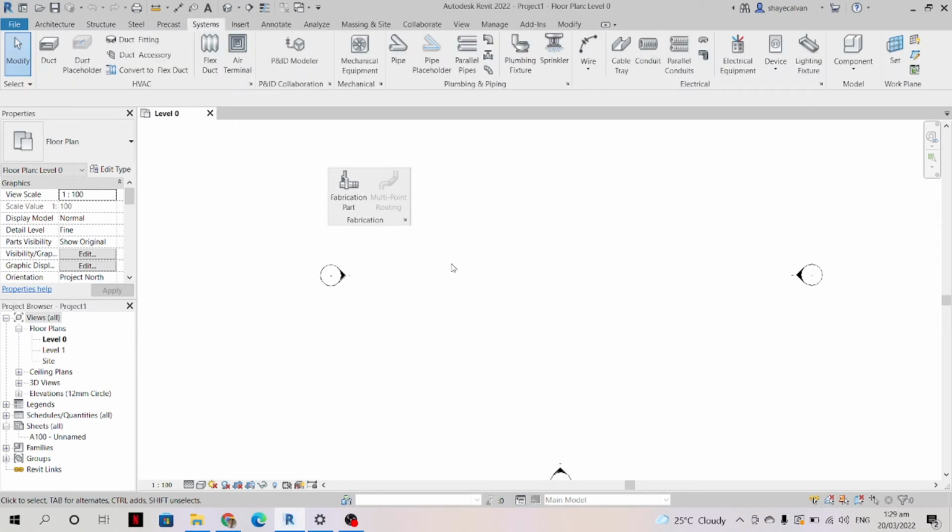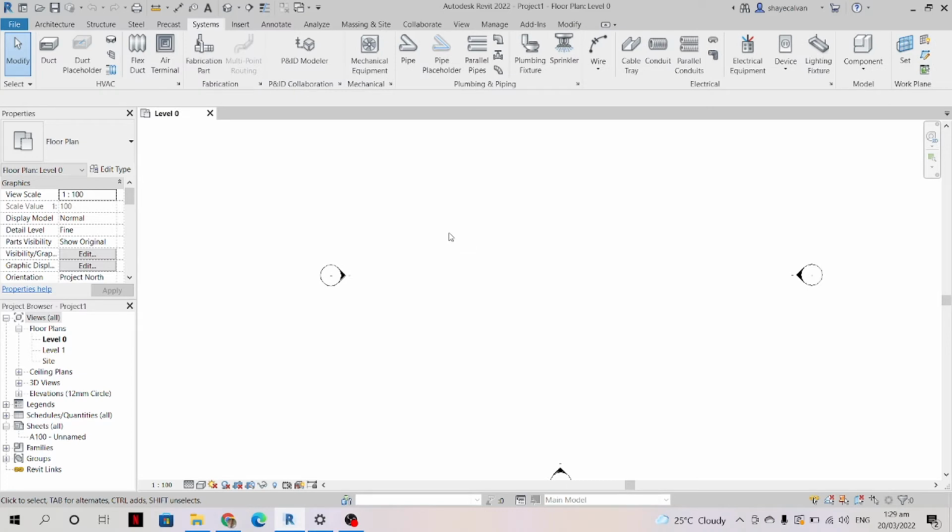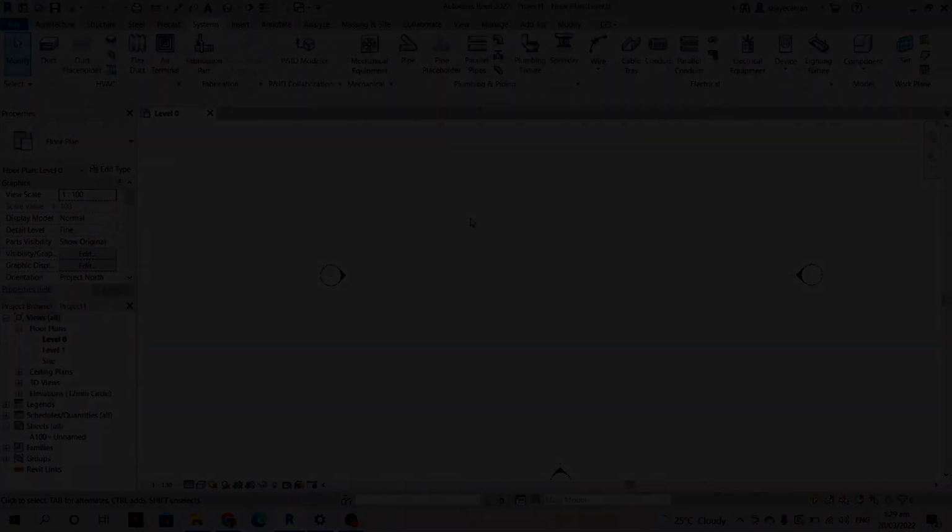To return the panel to the ribbon, hover the cursor over the panel until you see the sidebars and then click Return Panels to Ribbon in the upper right corner. This will return the panel to the proper ribbon and to the ribbon location it came from, even if that ribbon is not currently visible.